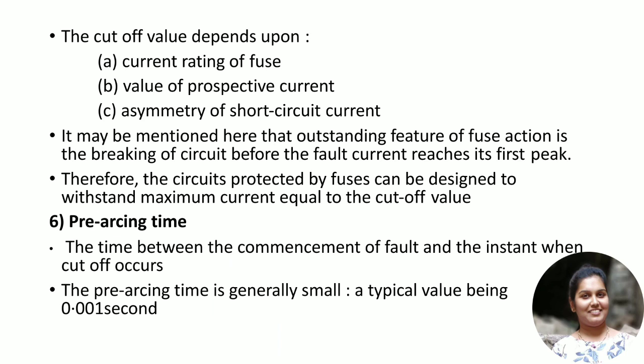So the value will be very small, and this small value indicates that the switching action of the fuse is very fast. The higher the value of this pre-arcing time, the slower the switching action is. That is, how fast the fuse works is decided by its pre-arcing time.